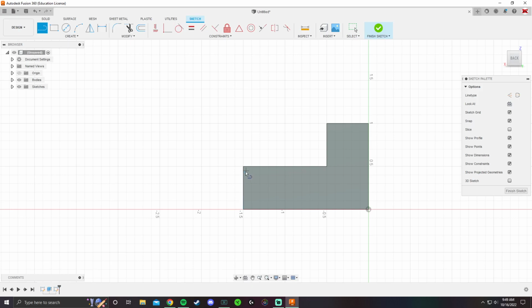I'm going to connect it to our known points on our top and our bottom. I'm going to go out. I'm going to go up, across, because we are making an L again, and I'm going to connect it. Now, maybe if this line was like this or something, make sure you just use your horizontal and vertical constraints to double check everything.